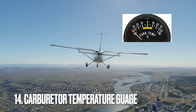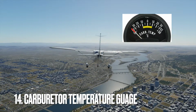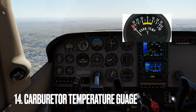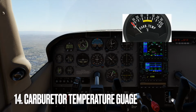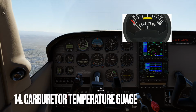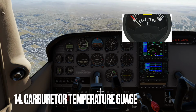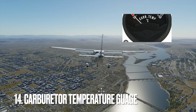The carburetor temperature gauge measures the temperature of the carburetor. Pilots use the carburetor temperature gauge to monitor carburetor heat and prevent carburetor icing, especially during cold weather operations. For example, during descent, the pilot adjusts carburetor heat to prevent ice formation in the carburetor throat, which could disrupt engine operation. Monitoring carburetor temperature helps pilots maintain engine performance, prevent icing-related engine failures, and ensure safe operation in icing conditions.